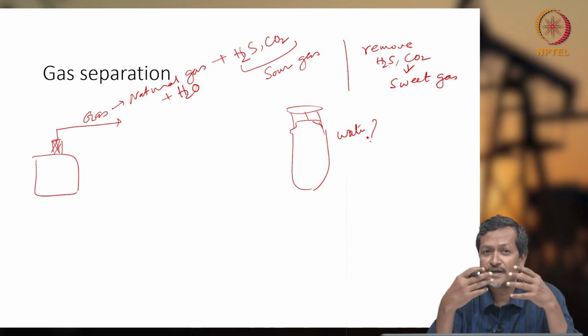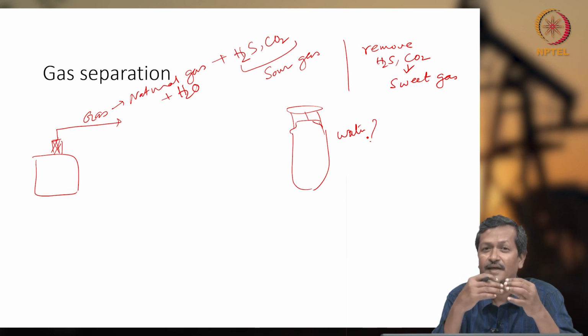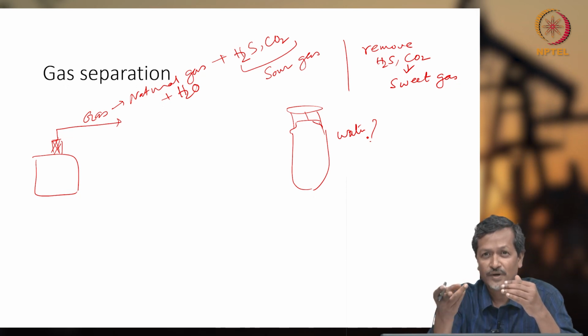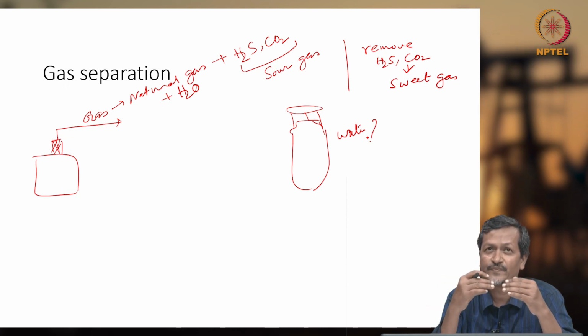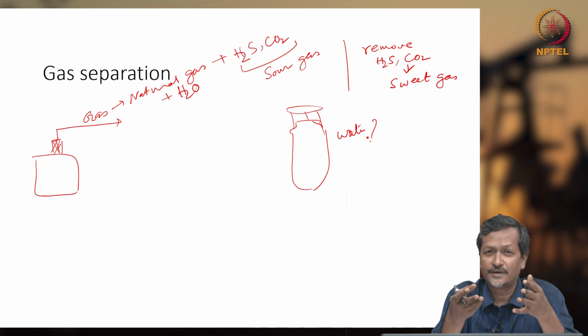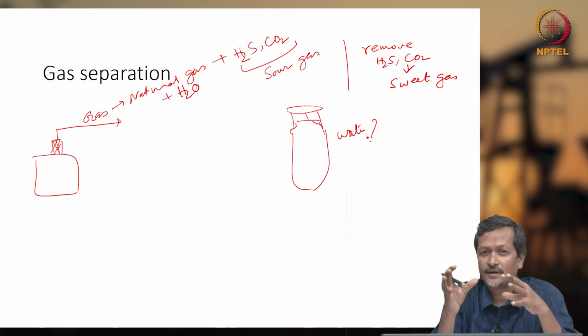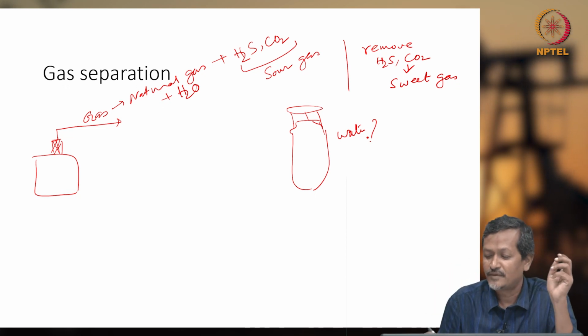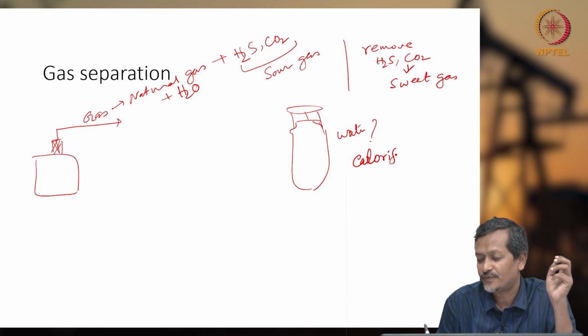And if you are burning, let us say, Indian gas, the gas will generate lots of heat, and the heat will be heating water also, and water will be producing steam. That latent heat taken by the steam, you cannot recover. So, that energy will be lost. Whenever you are burning coal or oil, there is a term called heating value, calorific value.